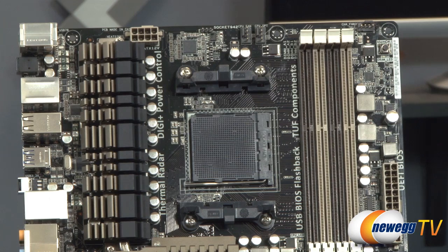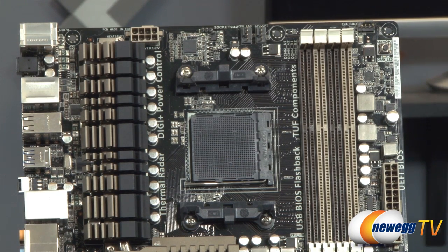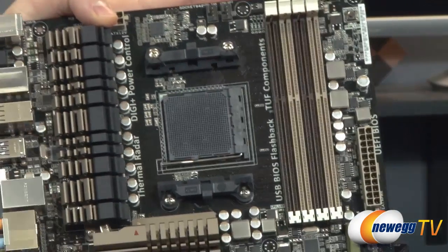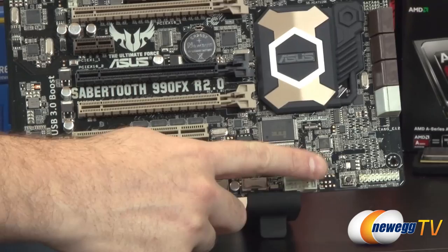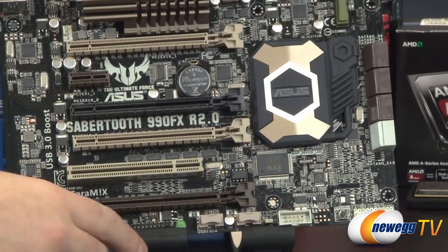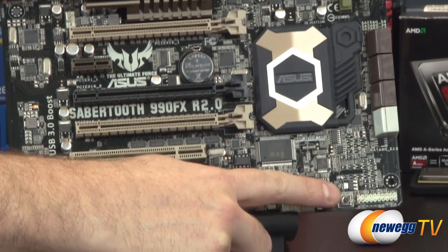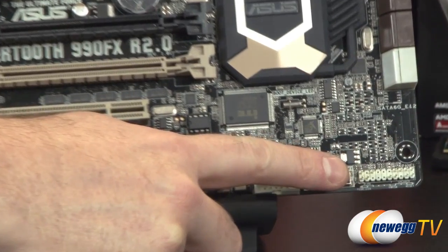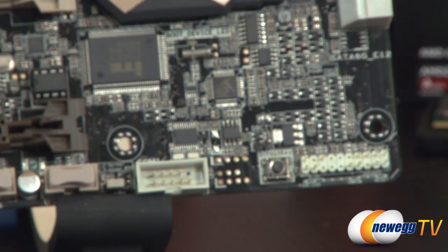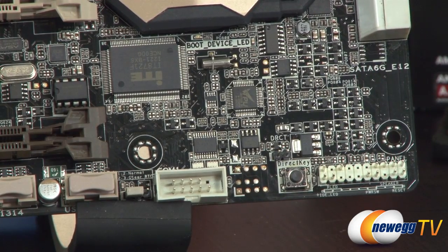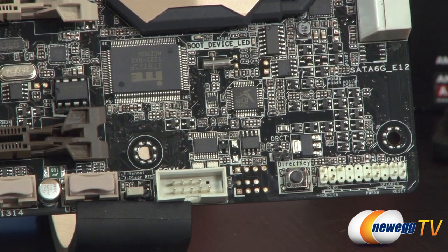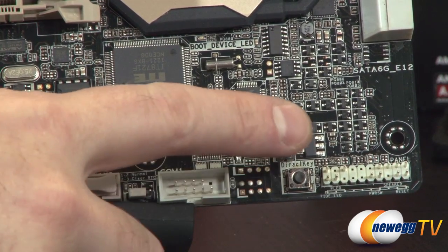Okay, so then we need to know, where are the front panel connectors? Front panel connectors are another element that we hadn't pointed out yet, but they're located in the very bottom right on this particular motherboard. That's usually where I find them, so it's this tiny little bank of white pinouts right there. Basically, if you have a computer case and that computer case has, say, a power button or a reset button, then there's some way for that button to connect to the motherboard to tell the computer to turn on. That is where front panel connectors come into play.